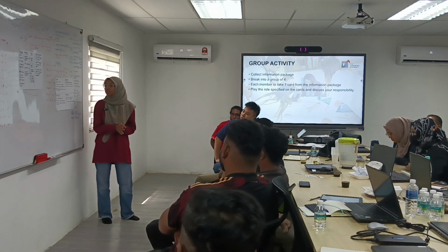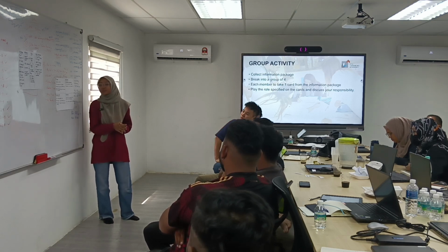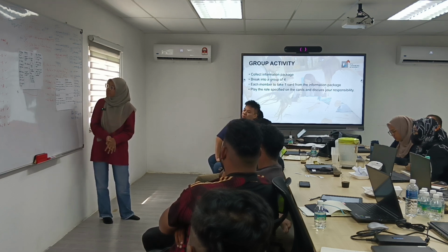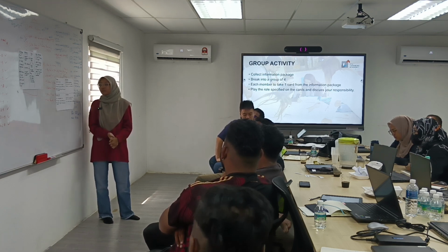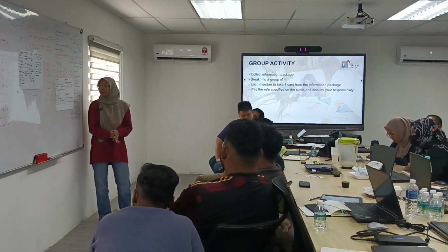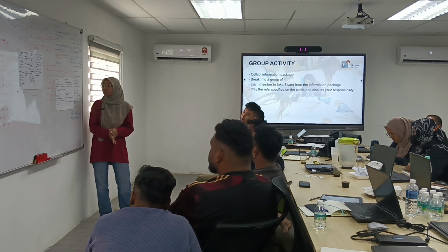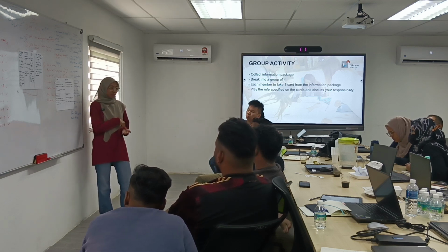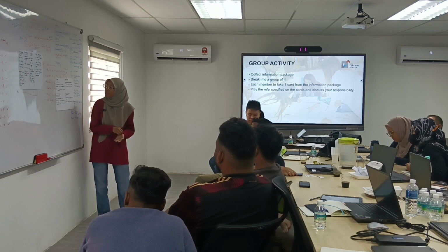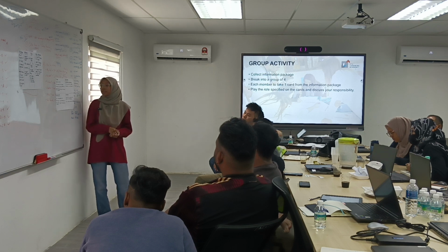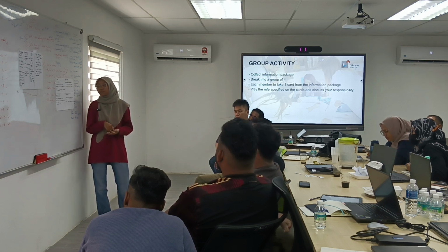So maybe I will start with the person that we work with the most now in JDC2 at site. The IOW, which is the inspector of works. For IOW, at site they will ensure the installation is as per approved drawings as per in our SharePoint, and then they will ensure the material on site is approved as per the approved MAF, material approval form, and also the works carried out are as per approved MOS.